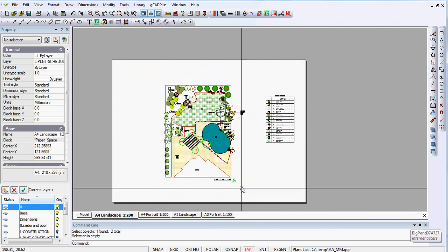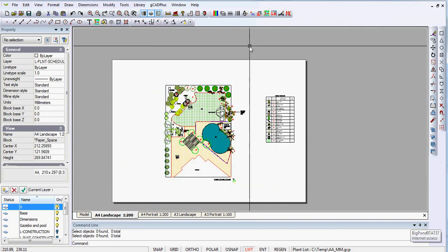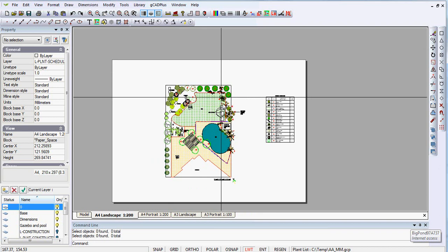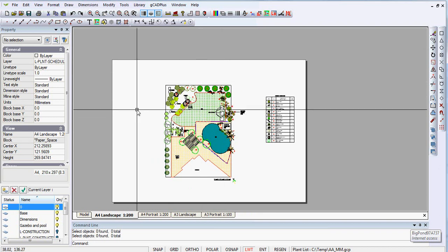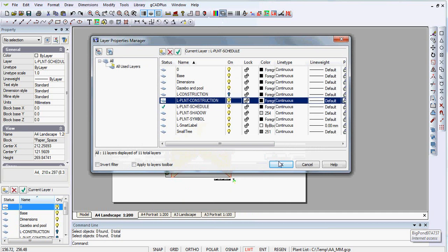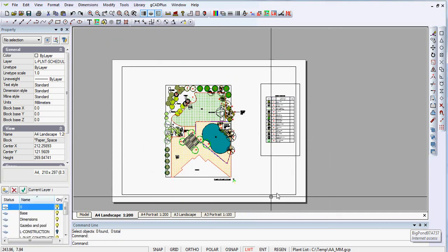So you can always pick them up again by just selecting, like so. That should pick up that frame. Because we've put it on a layer, haven't we, that has been turned off. We missed them. I was going to move that one over there. So let's just temporarily turn that construction layer back on. We should see the frames, and we now do.